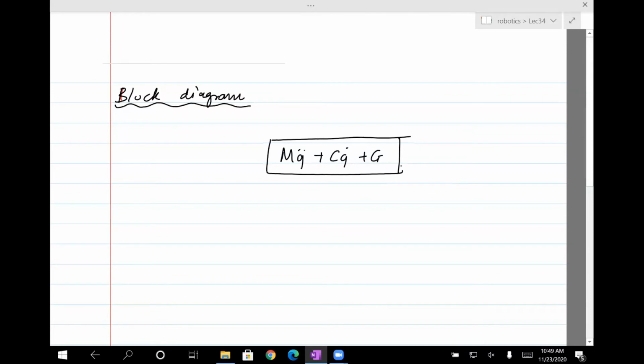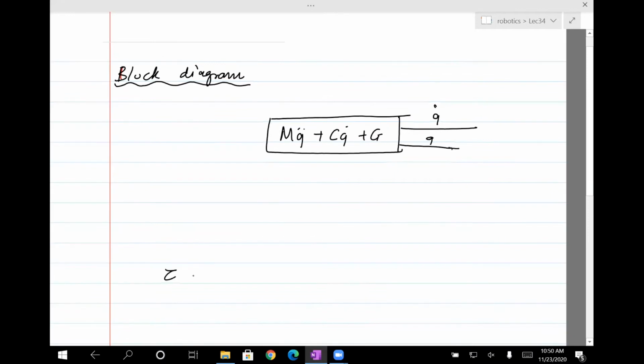What comes out of the system dynamics is a measurement for q dot and q, which is the position and velocity. We've written down the formula for torque, which is basically M times KP q minus KD q dot. It's 10:50, but give me a minute and I'll finish this and we should be done. Plus g hat plus c hat q dot.